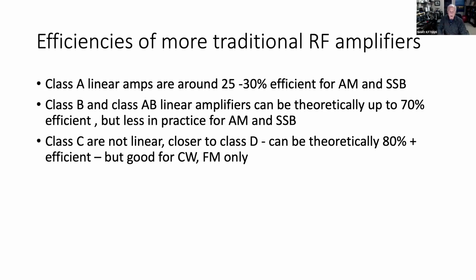However, their audio characteristics are not very good. They have a lot of distortion, and not just audio. They're basically not very pure. They don't generate pure sine waves because of technical issues at the crossover point when one, say transistor, is conducting and the other is not in a switch. There's a crossover point where they're going through 0 volts in the sine wave, and usually there's some sort of discontinuity there. So it creates some sort of distortion, and there's ways of getting around that. But they're efficient, but not that efficient. So again, they're used mostly for sideband and AM types of modulation.